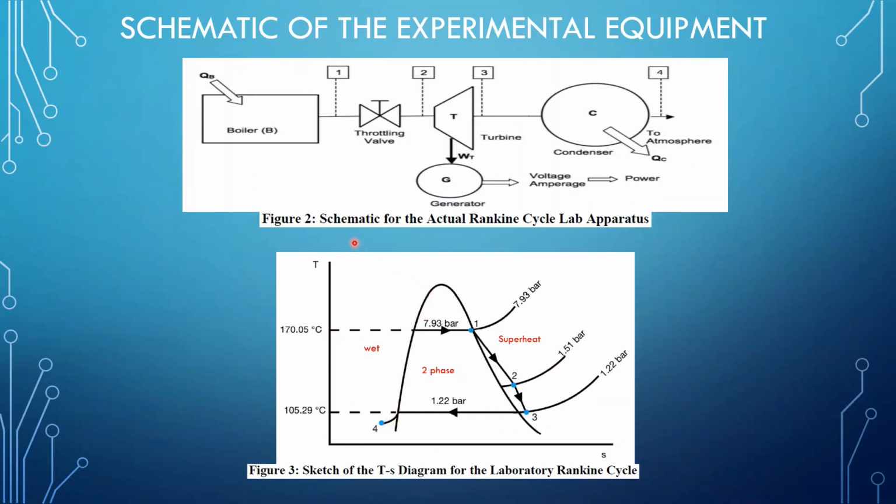Now let's just track back a little bit, go back to the start of the process, which is the working fluid in the liquid state. So on a typical Rankine cycle, as you would see when you do your additional research to produce your lab report, you would notice that the liquid begins in the wet region, in the liquid region, which is the water. And as you apply heat to the water, the temperature begins to rise as expected until we get to this point where we can begin the change of phase from the liquid to the gaseous state.